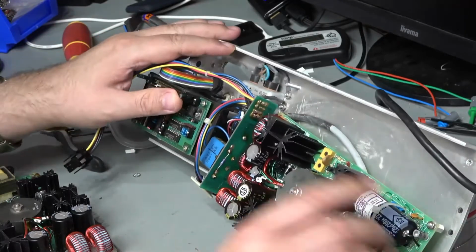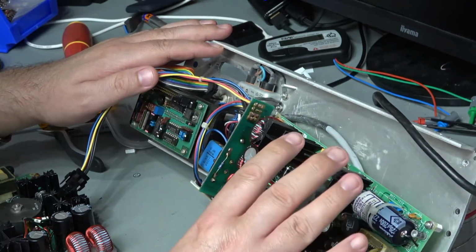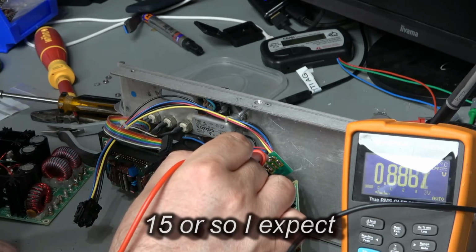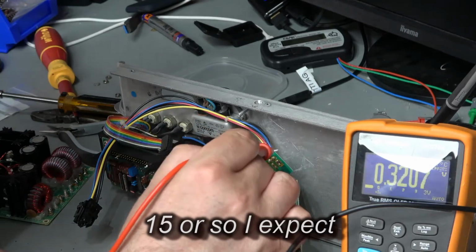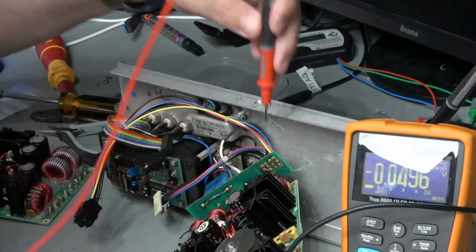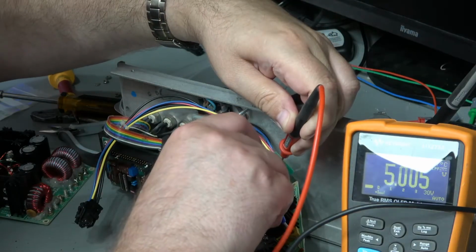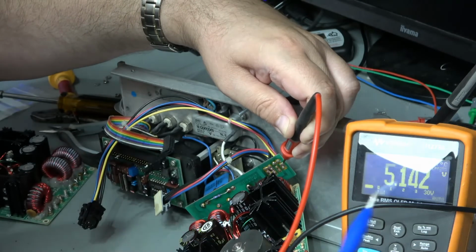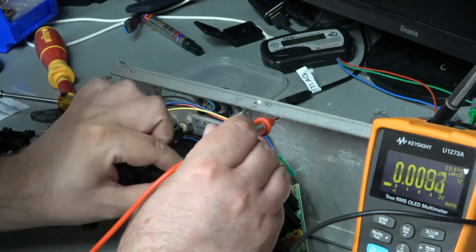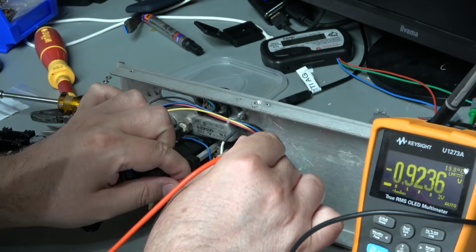Okay, so this is our new board in place. I'm getting 5 volts out of it. I'm not getting plus minus 15. So yellow should be 15 and it is just under 1. Here's my 5 volts. Now I do need to trim that up to about more like 5.1. That's because obviously there will be some voltage loss as we go down onto the main board. Okay, blue should be minus 15 and it's about minus 1.